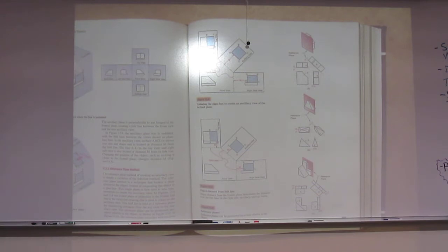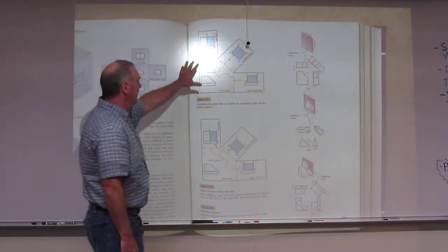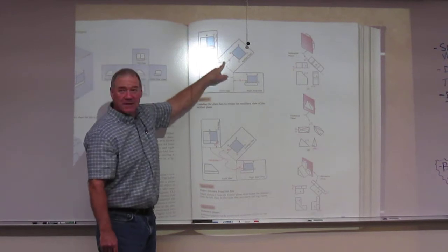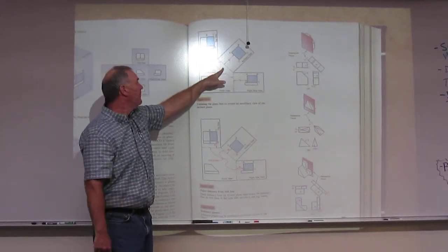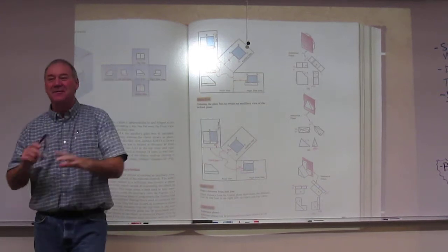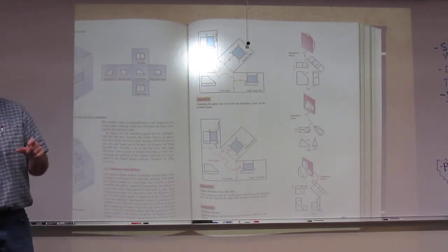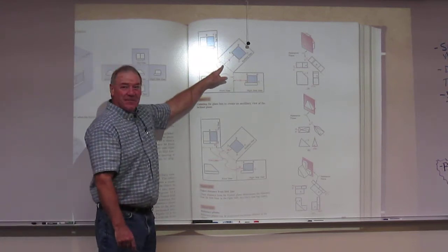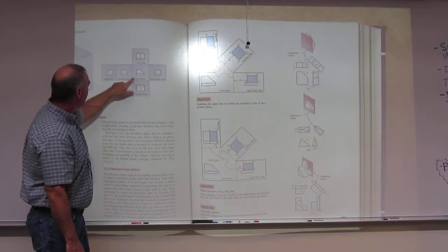Alrighty, so when we're looking at this page, the two ways they show you, one is what we call the fold line method of constructing these views. You're seeing it right here. Remember, a fold line, like this phantom line that's shown here, we usually use phantoms for this just to display it. Those lines, by the way, will not be on your finished drawing. We use them for construction and then turn them off and delete them.